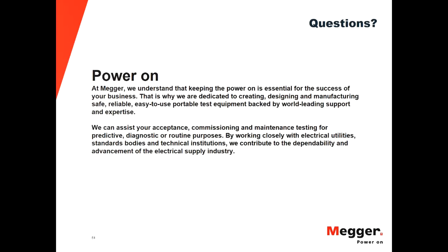All right, next question. In a battery bank, while performing a capacity test, say battery number 18 of 60, the voltage drops very low. Do you abandon the test or continue? How should we prepare for a retest? Replace number 18 first, or are other options available?